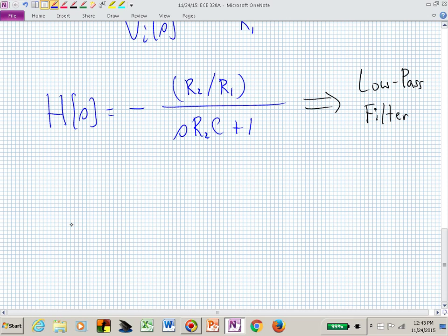In a very general sense, could you just say, oh, the magnitude is going to be flat, and then it's going to go down? Very basic sense, and that is only going to break once because it's first order. And where is it breaking? What is that point called? The break frequency.